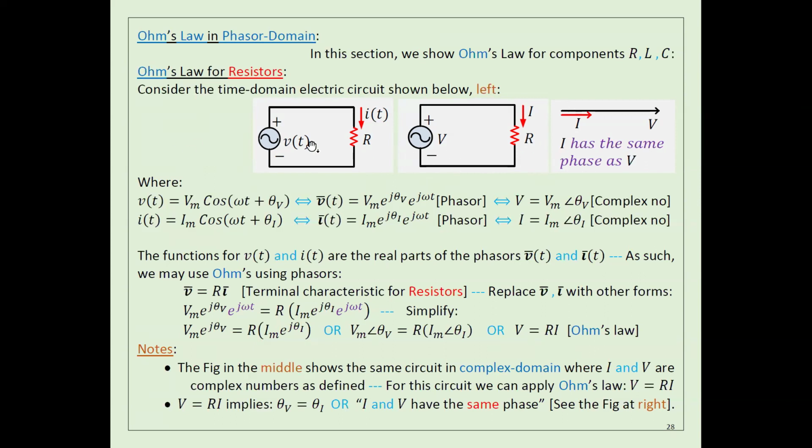But I want to bring your attention here, or clarify, that if it is a resistance, if you look at the angle between I and V, they have the same angle. A resistance does not change the angle. That means in exams, when you calculate the voltage across a resistance and the current, they should have the same angle, omega t plus 20, omega t plus 20, for example.